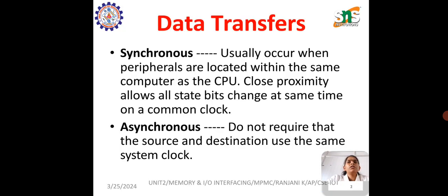So, what is memory interfacing? When we are executing any instruction, we need the microprocessor to access the memory for reading instructions, codes, and data stored in the memory. For this, both the memory and the microprocessor require some signals to read from and write to the register. The interfacing process includes some key factors to match the memory requirements and the microprocessor signals. The interfacing circuit should therefore be designed in such a way that it matches the memory signal requirements with the microprocessor signals. So this is memory interfacing, and next is I/O interfacing.